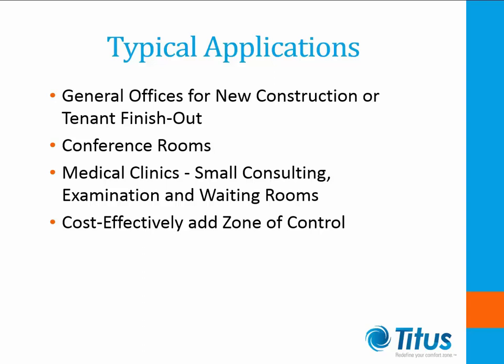This leads to a good question of what are the limitations of variable air volume diffusers. VAV diffusers work well for smaller installations or smaller subsystems in installations, but can have a limited range of operating conditions when compared to the variety available with traditional systems. Also, varying the geometry can vary the sound generated by the diffuser. The thorough designer will check the range of temperature, airflow, and sound levels when choosing a VAV diffuser system.